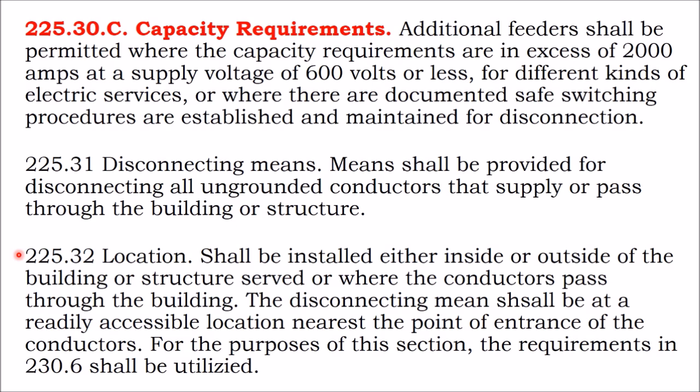And so, basically where this boils down to is no matter where you are with solar, your utility is going to want to see an external disconnect switch at the point of entrance where the power enters the property that can turn off your solar array, so that when they're pulling your utility meter to turn power off to the property, they can also flick your solar switch and turn the solar array off as well.